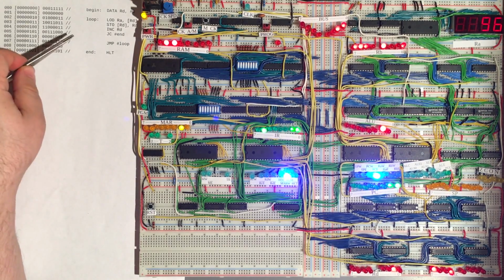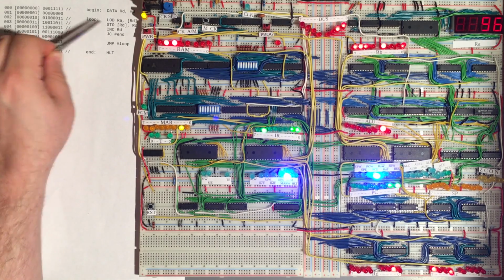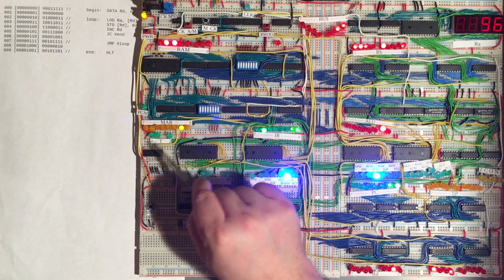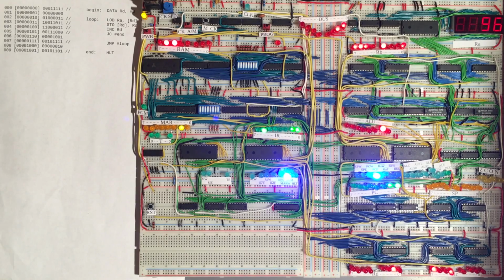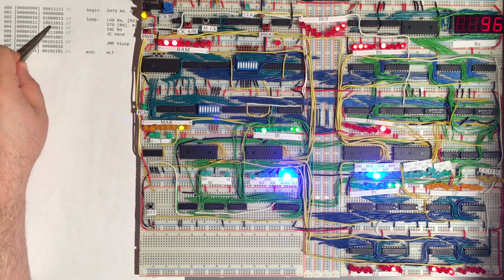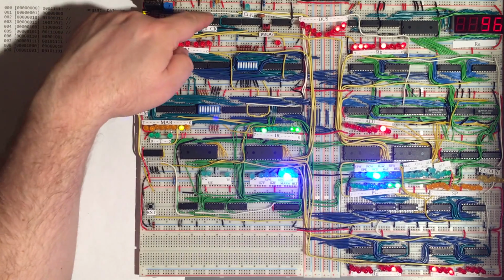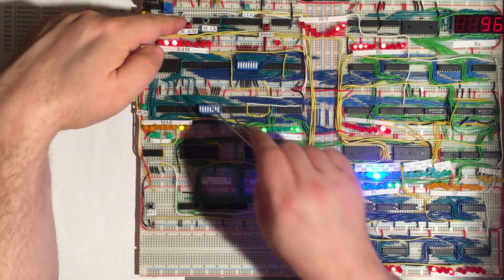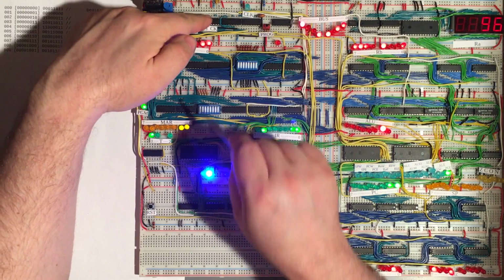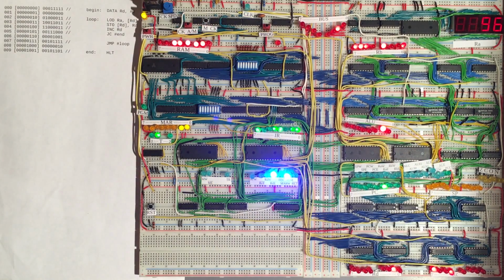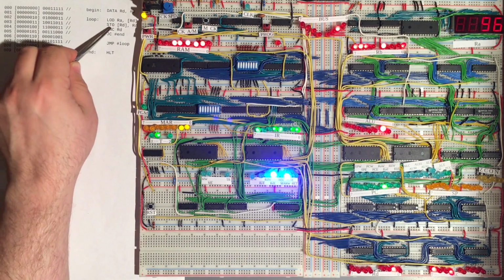Now a store instruction, this next instruction happens to be a store instruction. So once again, we're at time t0 and we're at address 3. So we're now nicely pointed at this store instruction. So again, the first two microcycles are the same. We need to get the instruction from program memory, which is at this address, and then load it into the instruction register. But then now we can have a look at the microcode for the store instruction.